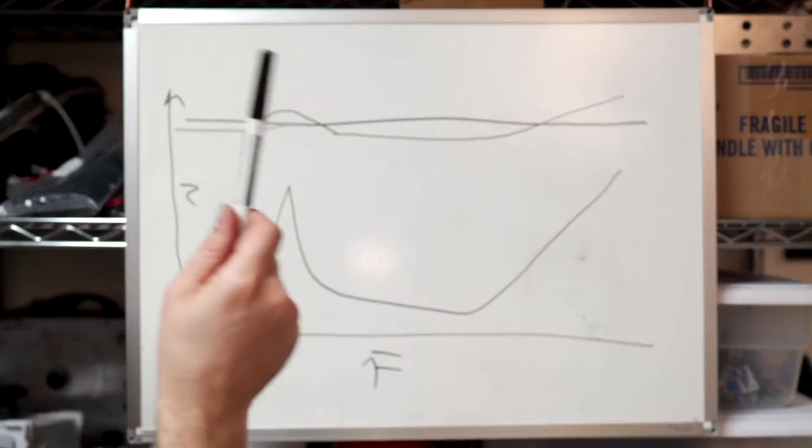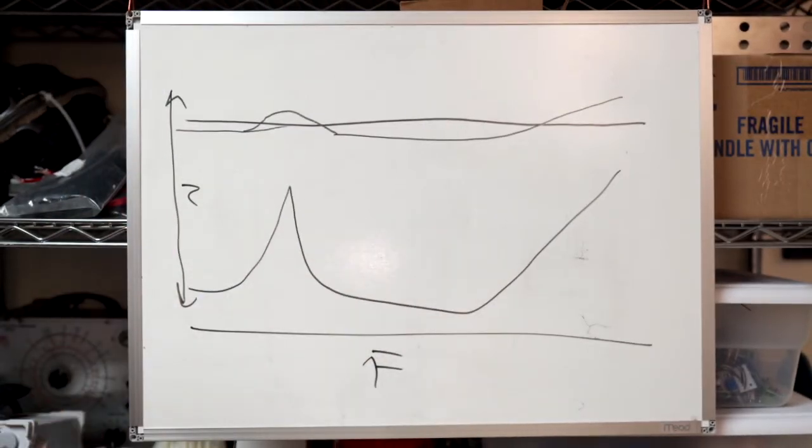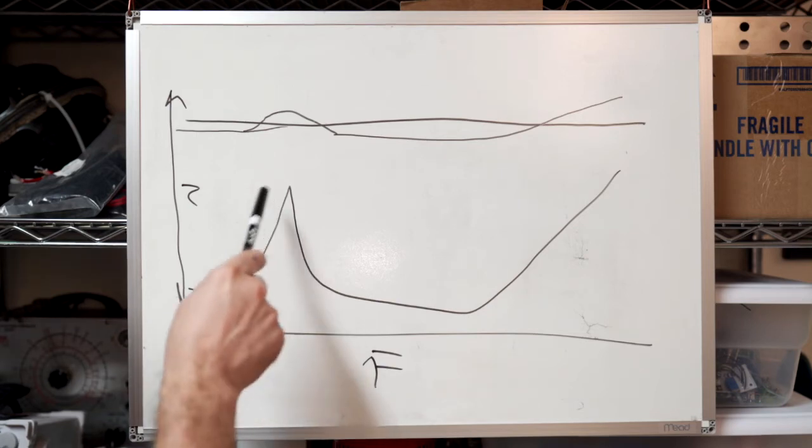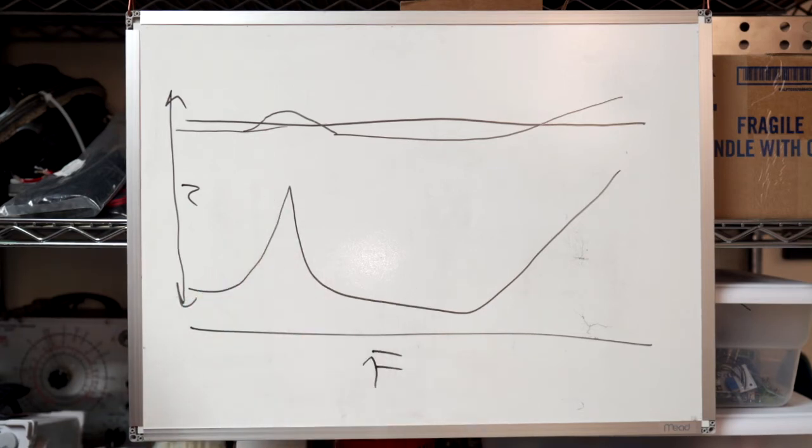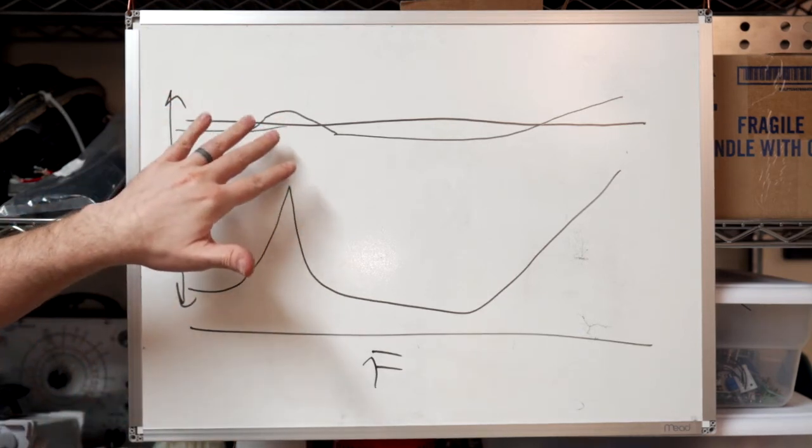This might be some of the reason why some speakers sound better with tube amps than solid state amps. If this is a woofer, for instance, resonance a lot of the time is down in the 35, 40, 45, 50 hertz range. That's actually a pleasant range for a little bit of bump in the low frequencies, a couple few dB or something like that.